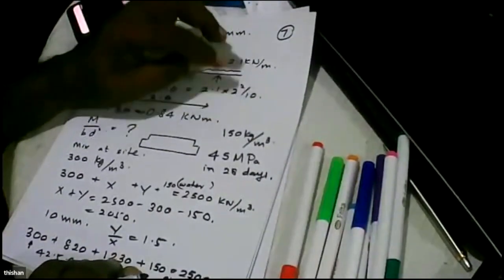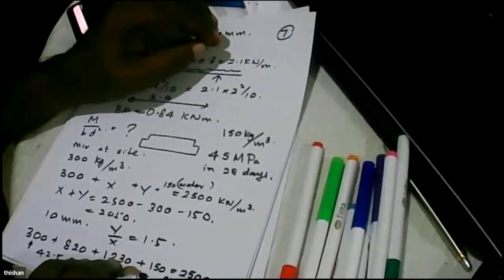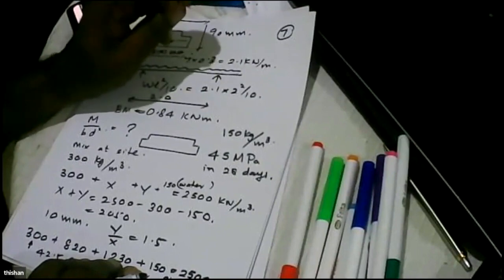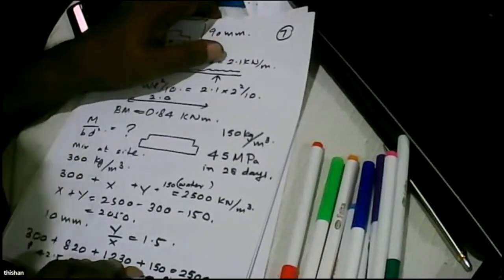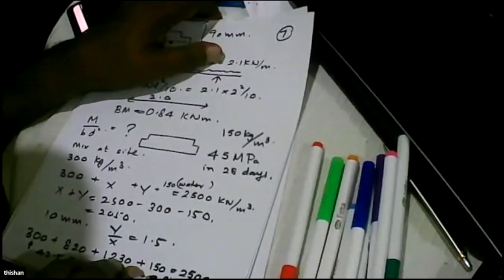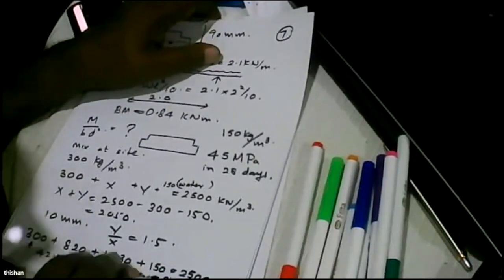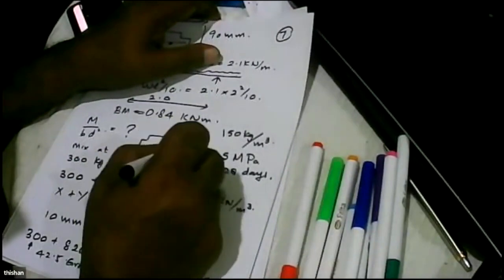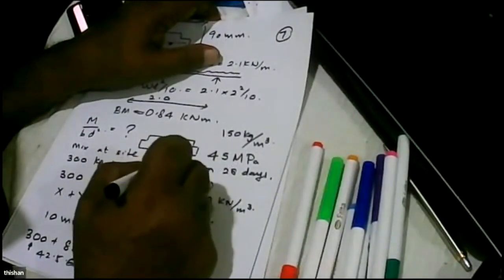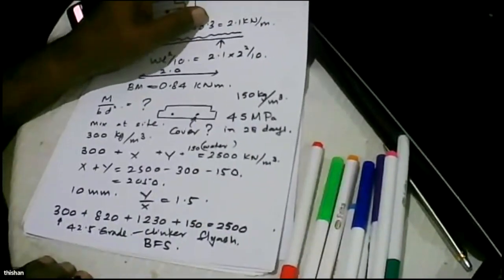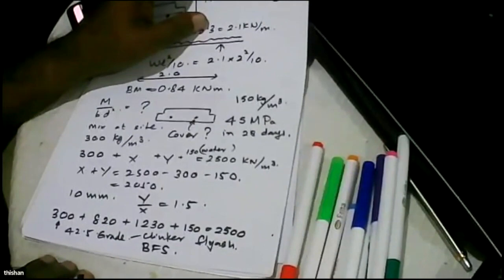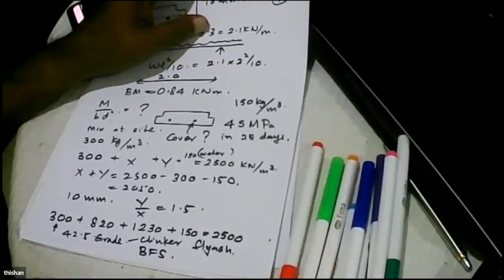And we are trying to use 150 or even less. We'll use the minimum water. The moment you use minimum water, we get a maximum benefit. And we are not casting a big section. We are just casting a slab. So the question is, what is the cover? We are designing according to Eurocodes. Now we are looking at the Eurocode.